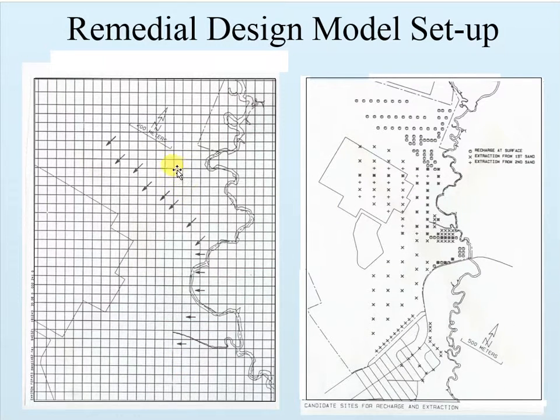The remedial design setup for this site involved a MODFLOW-based simulation model, the imposition of gradient constraints or head difference constraints indicated by the arrows. So wherever there's an arrow, we required that the head at the upside end of the arrow be greater than the head at the downside end of the arrow by a certain difference to induce a capture zone. We also impose that vertically at many locations, which are not shown here.